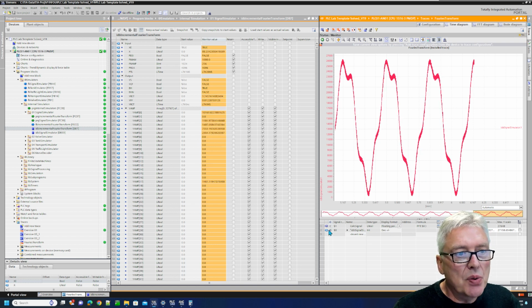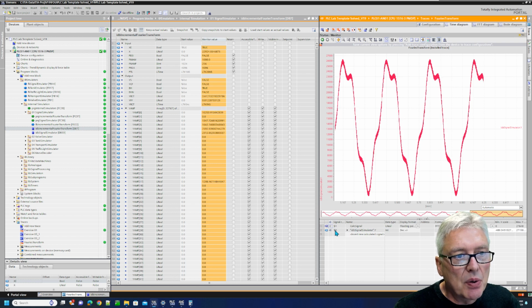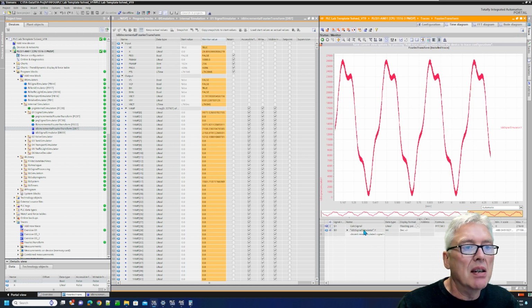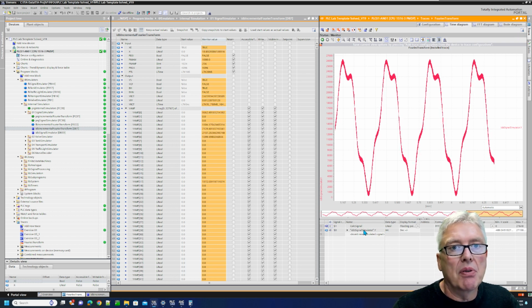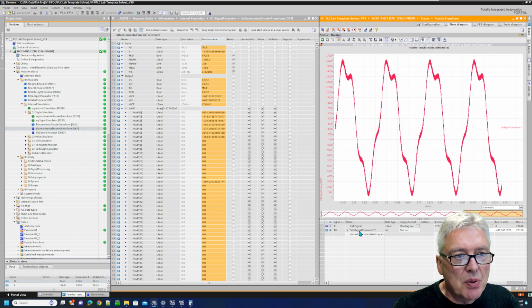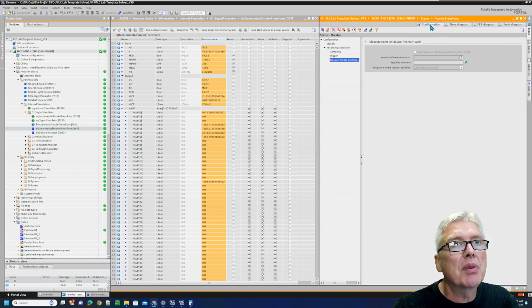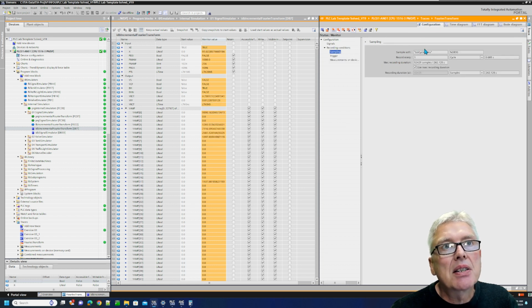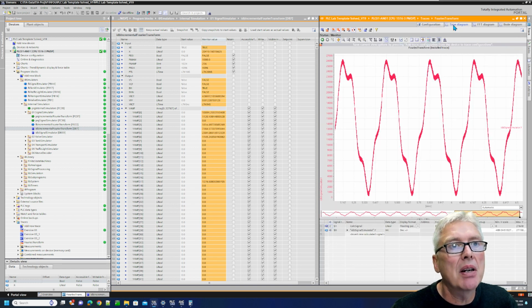What you have to do is add a signal here. We have a signal simulator, and for one odd reason, it has to execute on an interrupt. So this signal is generated on every interrupt. I think we can see the configuration here. It's a 5 millisecond cyclic interrupt, and I record every cycle here for the time diagram.